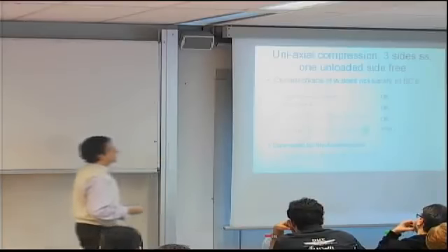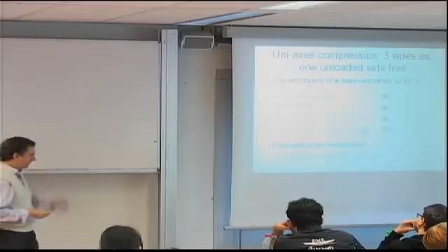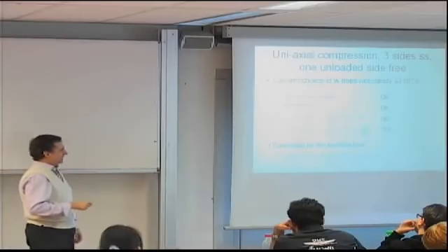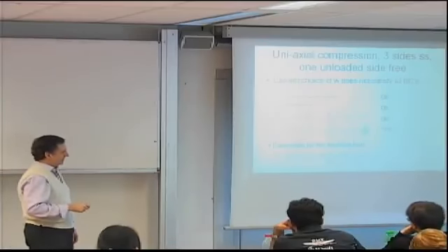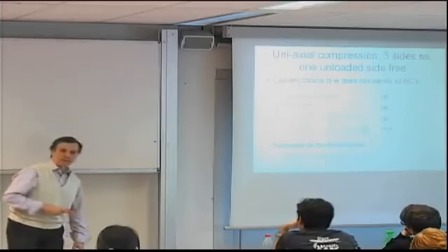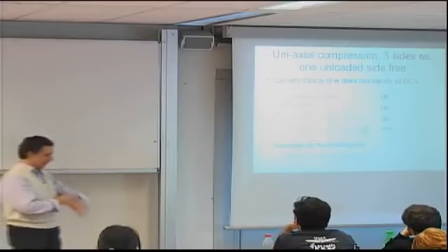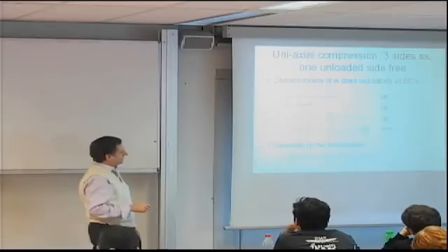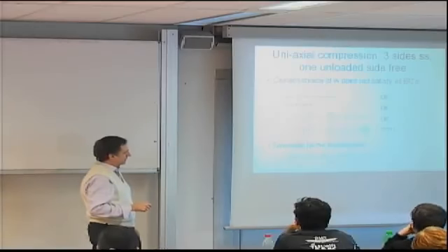If I go through the exact same procedure we did before for the simply supported case, I will find this expression for my uniaxial compressive buckling load, N0. And the only difference from before is this lambda that appears in these two locations here.